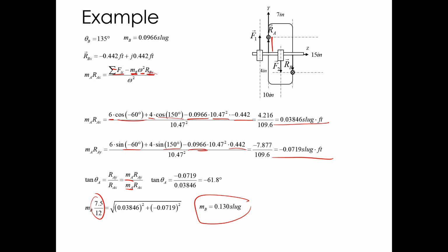Because what's going to happen as you spin this faster, these forces go up with omega squared, and you get more signal to noise on your transducers. So you're going to want to spin things up to pretty close to their maximum allowable speed to balance if you want to do as good of a job. You're going to get more signal to noise on your force transducers if you spin things faster. For tires, they're so compliant and they deform on the road and they get bigger as they spin faster. It's going to be hard to do a perfect job. So you're really just looking for decent on tires. Turbocharger impellers, you need better than decent. You need a good job of this. So you want to spin it faster and get more force, more signal to noise.